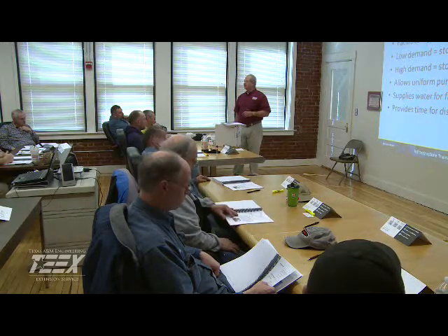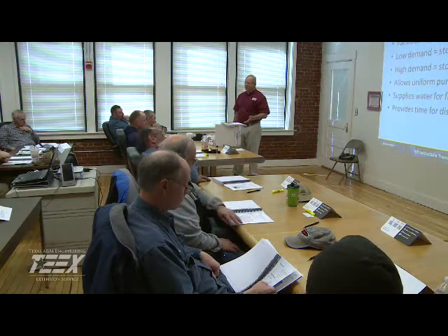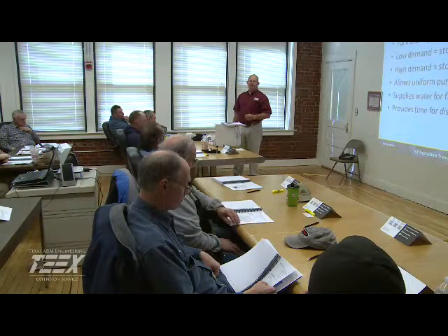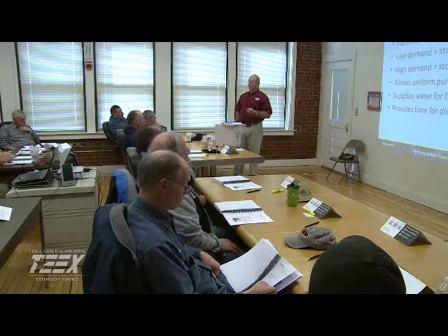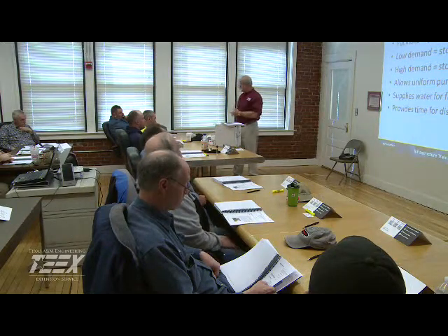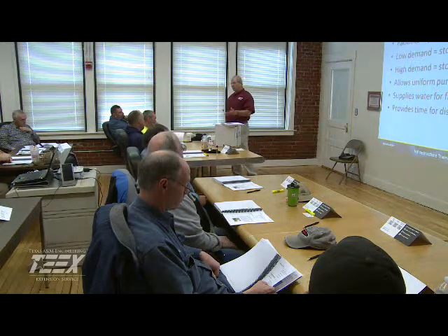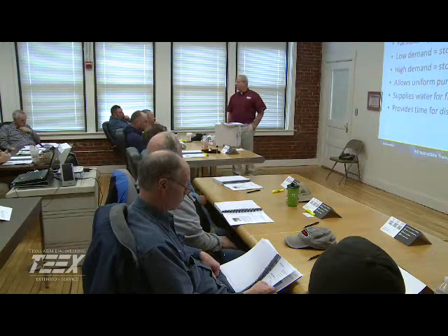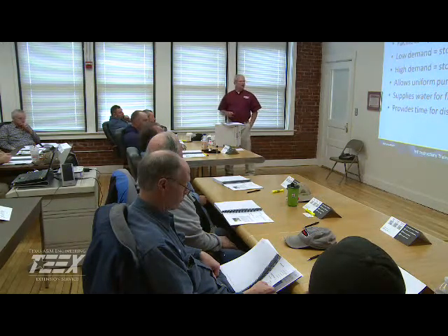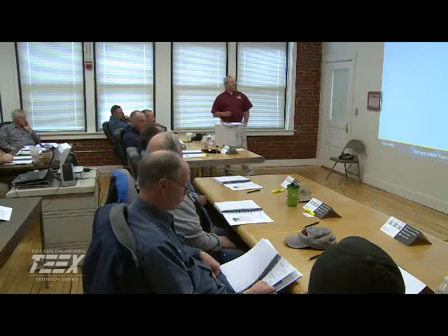So we're going to get in there. The basic thing, can you change the capacity of the storage facility? No. So the only thing that we can do to adjust for CT is what? Increase the dosage and raise the residual enough to where we can be assured that we meet the CT values for that particular system, okay?